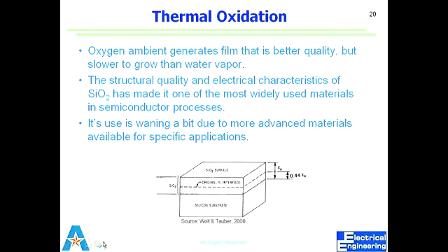So we need some other material which has the same dielectric contribution but is physically thick. So we use high K dielectrics, in which, with high K and higher thickness, the end electrical coupling is the same. Right?